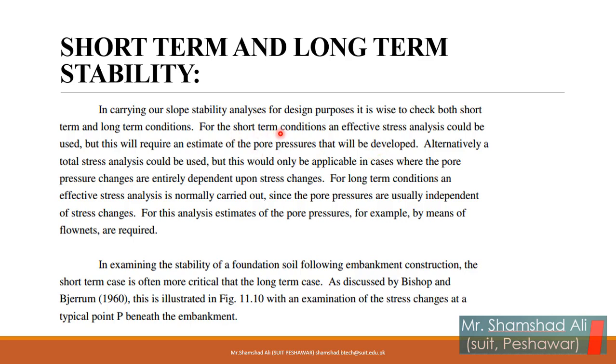For the short-term condition, in an effective stress analysis, the pore water pressure will be estimated. Alternatively, a total stress analysis could be used, but this will only be applicable in cases where the pore pressure changes are entirely dependent upon the stress change. For the long-term condition, an effective stress analysis is normally carried out since the pore pressures are independent of stress change. For this analysis, estimates of the pore pressure, for example by means of flow nets, are required.